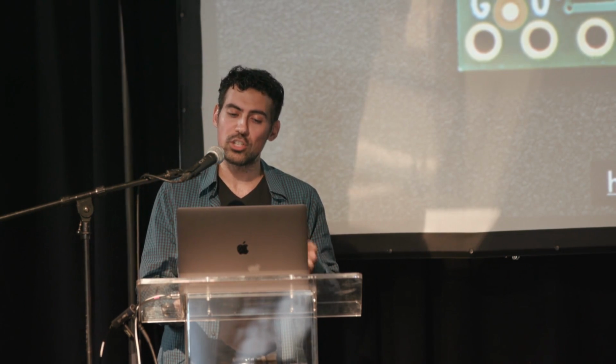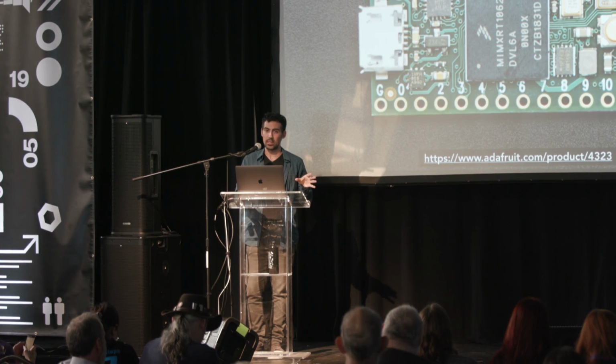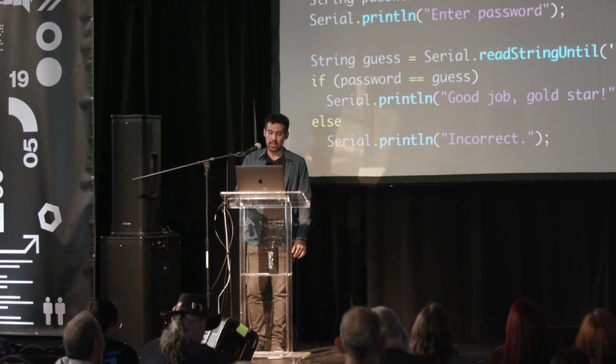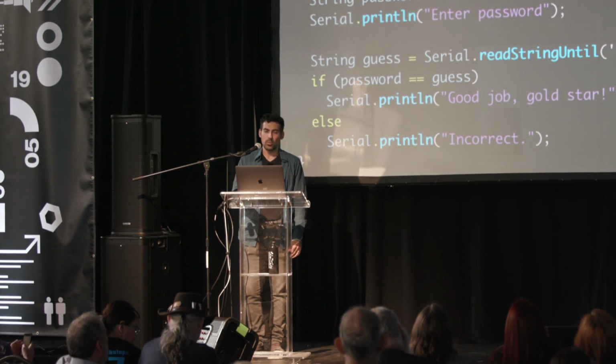Teensy. Okay, the new Teensy 4 is just a beast, right? 600 megahertz, but you can use even a Teensy 3 to do these types of attacks. So originally I was using the FPGA to do a lot of these attacks, and I just wondered, can I use a Teensy? Because that's something that many of us have, and the answer is yes. I'll provide a bunch of code so you can perform fault injection and side channel analysis using a Teensy in the 3 series. So one more example that I think is pretty interesting. What's wrong with this code?